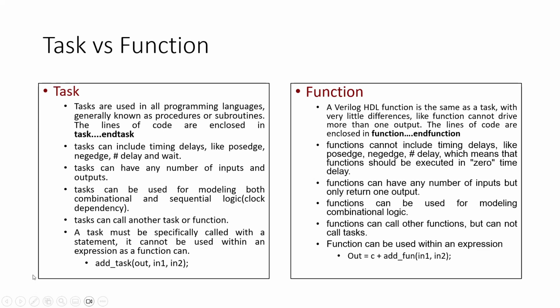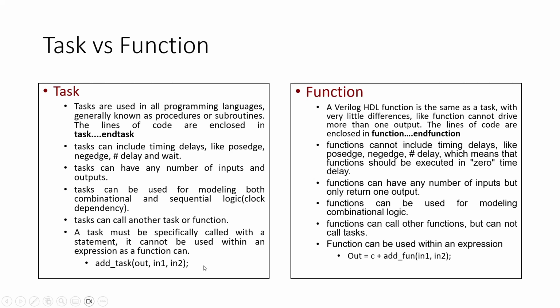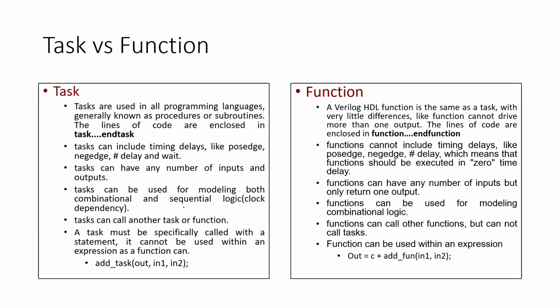So next one is tasks and functions. How are we executing the tasks and functions in our Verilog? A task can be executed with delays. A function is executed in zero simulation time. Whenever you are using a function, it will be executed at zero simulation time.